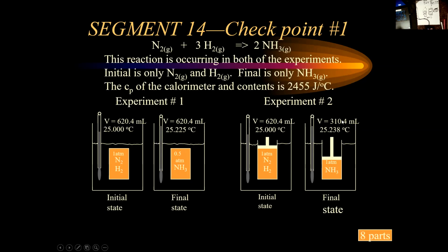So now let's think. I'm going to calculate Q for each case. Number 1 is Q at constant volume. What's that equal to? No, I'm not going to tell you. Go look it up. We just talked about it. This one's going to be at constant pressure. Q at constant pressure. It's CP delta T. So we got the heat flow. We got the temperature change. So we know what the number is. This one's going to be Q at constant volume with a sign that we can assign here. This is going to be Q at constant pressure with a sign that we can assign from here.